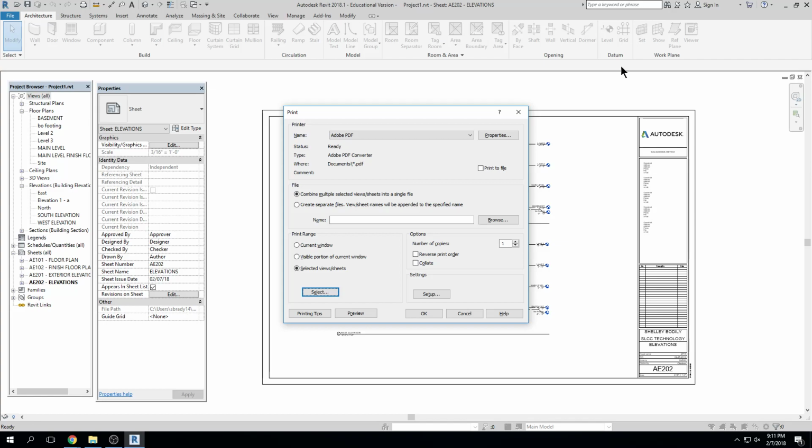And now what we're going to do is set up the print. So I click on setup. Oh boy. That's not available either. So I'm going to look at Paul's over here. Okay, so when I click on setup, the paper size is the first thing you're going to choose. It'll be 24 by 36, arch size D, 24 by 36.